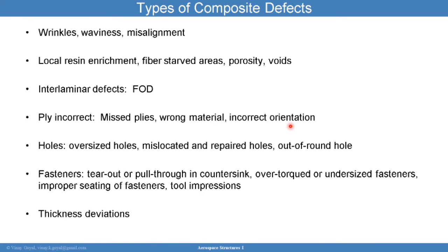That also decreases the strength of the composite. You could have porosity and voids within the composite. Too much porosity and voids within the resin can lead to a strength reduction, because those are stress concentrations, and the stress concentrations will then be crack initiators to micro cracks, which I'll cover very soon.